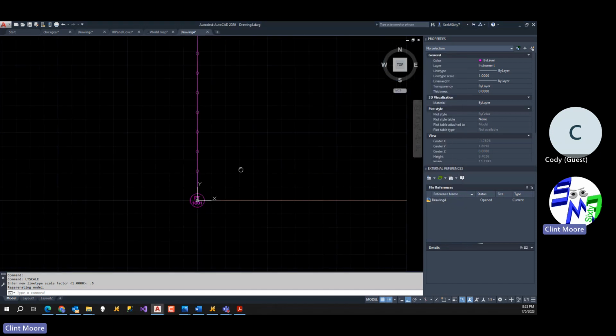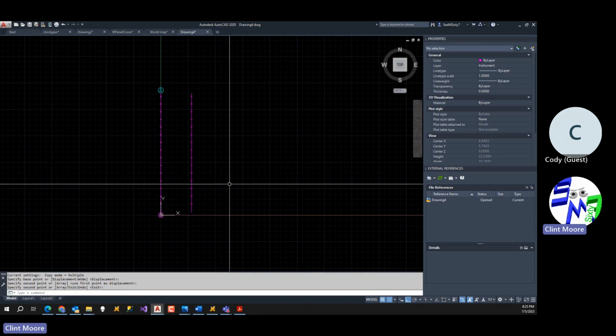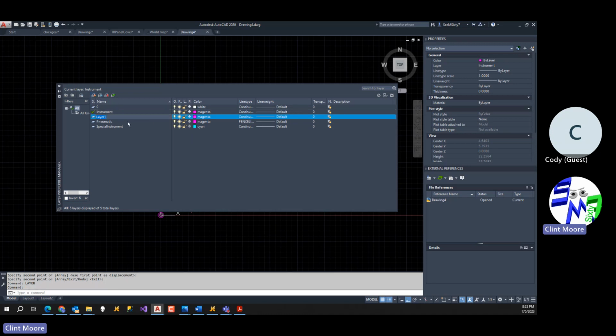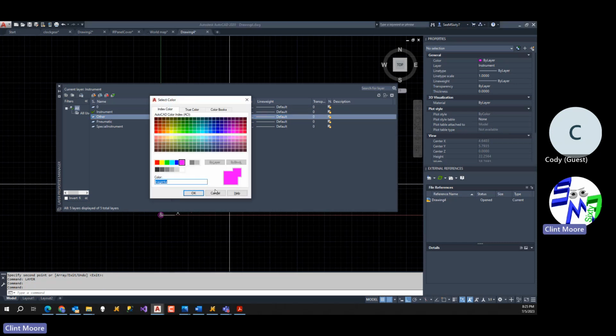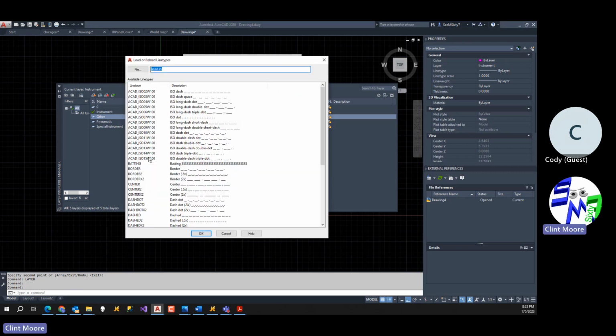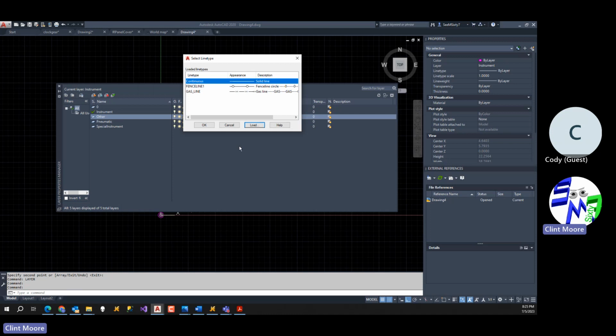And what we're going to do is actually draw another line type in here as well. I'm going to copy this one over here. I'm going to create another layer, and we're just going to make another line type layer that has text in it. Other. And we're going to pick another line type. I'm going to pick, oh, not that, not color, line type. My bad. Load, and we're going to scroll down through here again. And you see hot water supply, you see gas. Okay, so I'm going to use the gas line here as well, just so you can see what the style looks like when you actually have text inside your line. Okay, so we click on gas, pick OK.